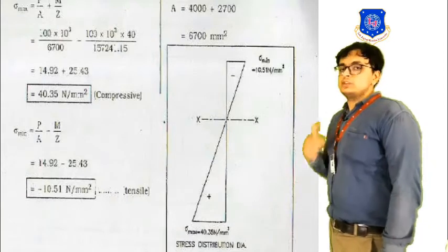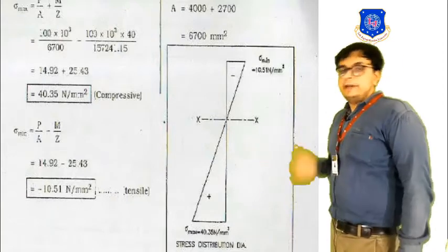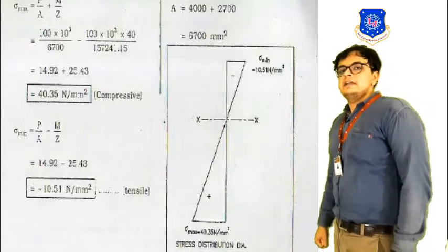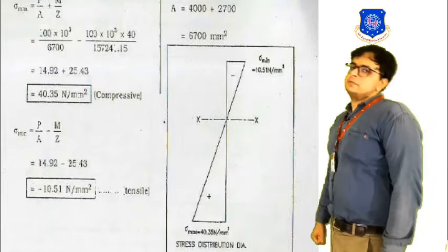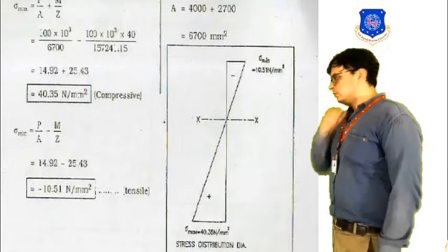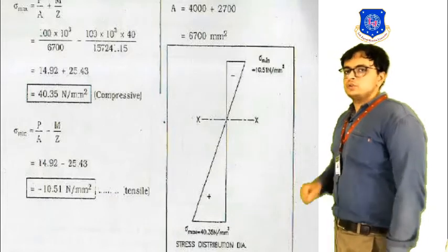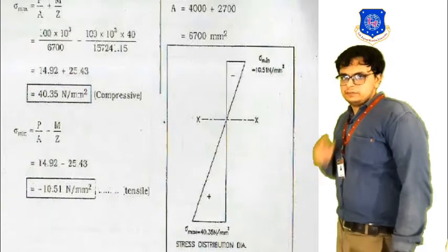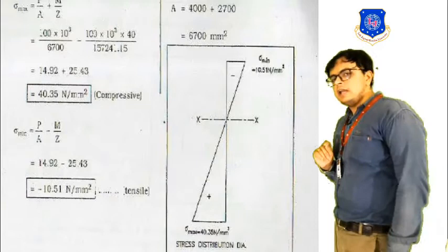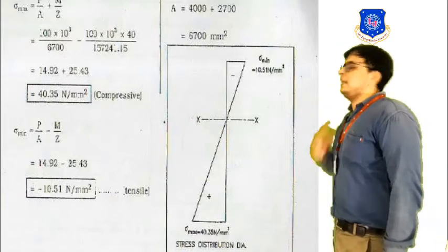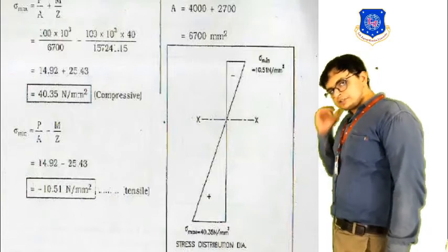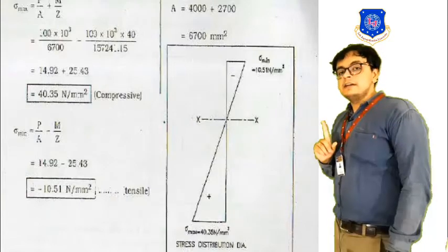So, we have to subtract the bending stress from the direct stress, and by this we will be getting the minimum stress onto it. So, let us start with its value. First of all, we require the direct stress, that is sigma 0. Its formula is just P by A, means the axial load that is acting onto a structure, that is 100 kilonewton.